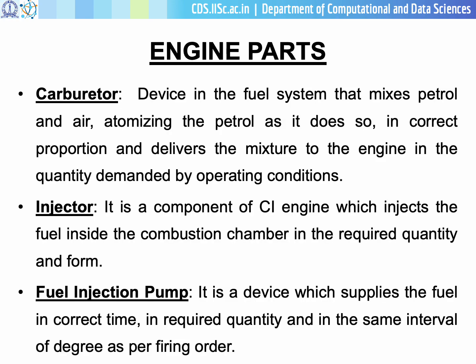Carburetor. It is a device in the fuel system that mixes petrol and air, atomizing the petrol as it does so, in the correct proportion, and delivers the mixture to the engine in the quantity demanded by the operating conditions.